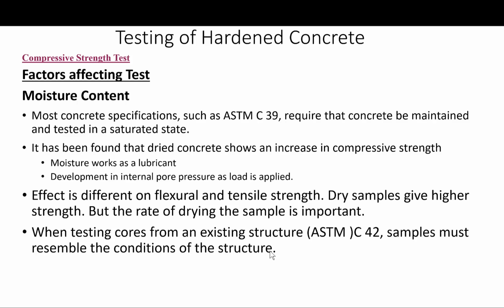The next factor is the moisture content. Most concrete specifications, such as ASTM C39, require that concrete be maintained and tested in a saturated state. It has been found that concrete that has been dried shows an increase in strength. The reasons for this are not completely understood.